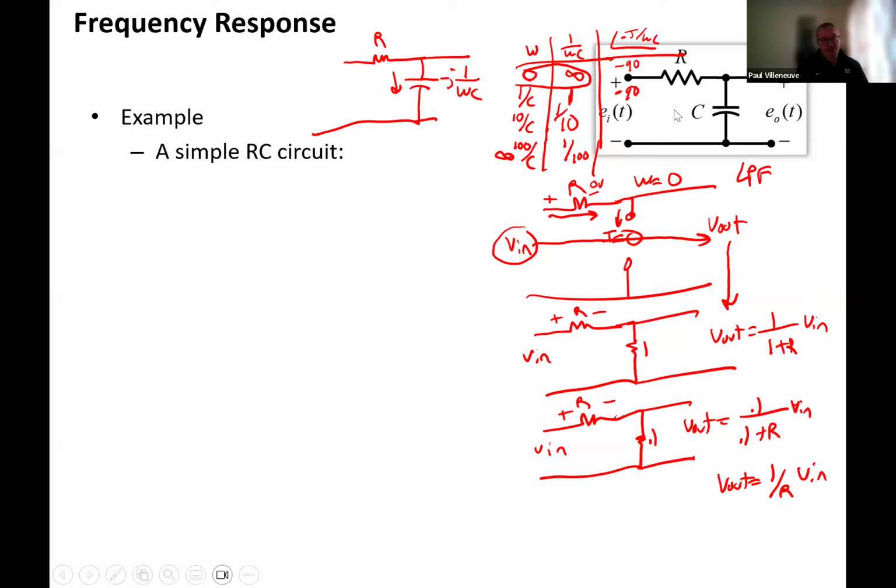And these are pretty simple. This is just an RC circuit. And you can move the capacitor position. So as Howard pointed out accurately, the location of the capacitor and resistor changes it from a low pass filter to a high pass filter. So just for fun, if you want to do a little practice, try doing this one using general analysis, and see if you get the fact that this is a high pass filter. By the way, can you do this work with inductors? Can you substitute inductors for capacitors? Anybody?